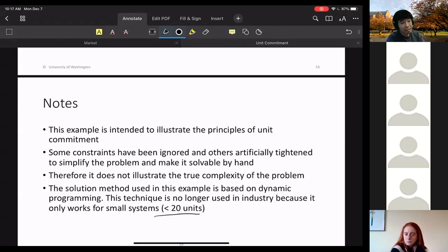Okay, so this is a good illustration of one way to think about unit commitment for multiple time periods, but again, that's not really the algorithm we use in practice, because the system can be potentially very large, right? But this does give us a feeling of how to solve this kind of problem and all the complexities that may arise, because there's minimum up, minimum down, these kinds of constraints on the generators. Any questions about this procedure?